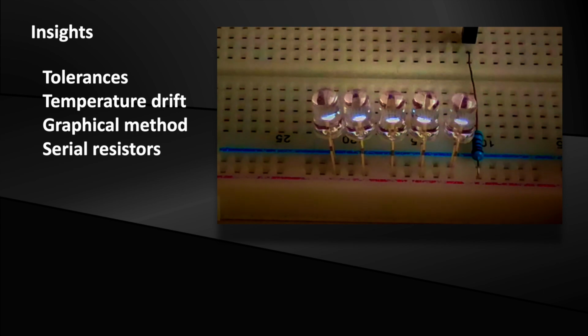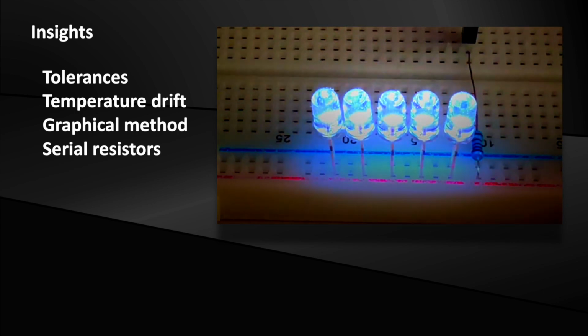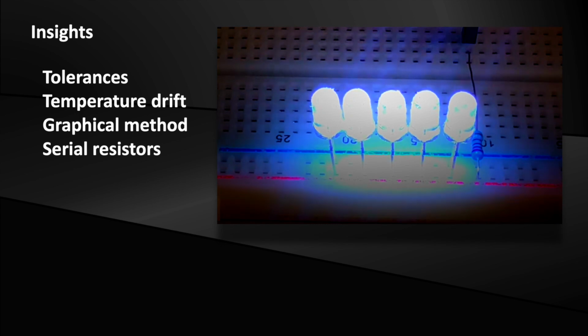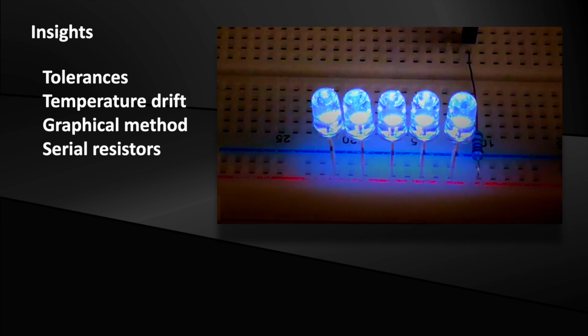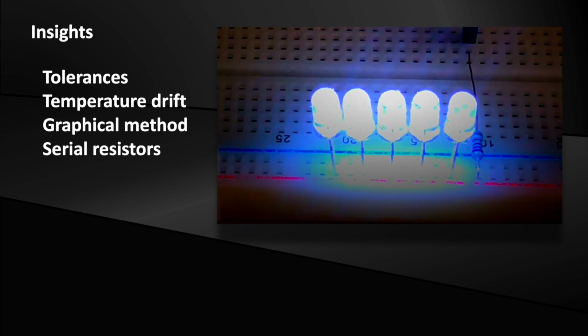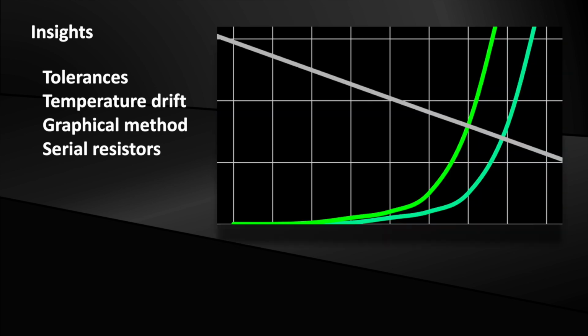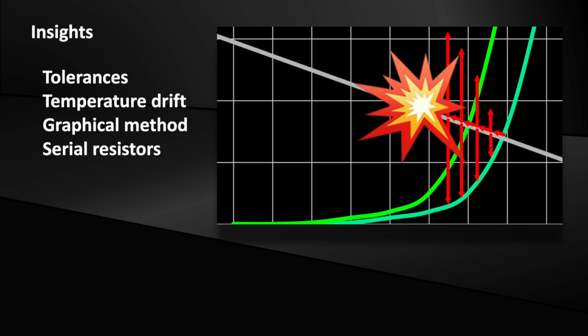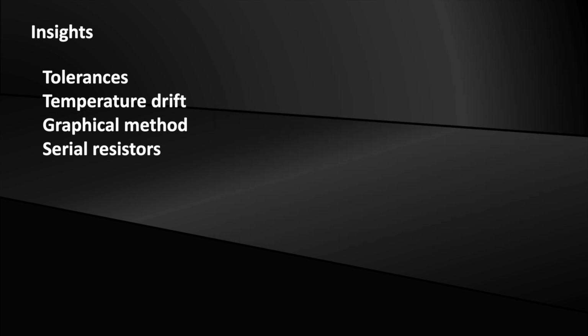Parallel connection is okay for operating same color LEDs at low current. Actually not recommended in the textbook, but possible, because LEDs today's manufacturing tolerances are small. At high current, however, it can be dangerous for semiconductors in general. Negative forward voltage temperature coefficients are driving the arrangement out of control. In case your supply voltage is high enough, connecting LEDs in series is the solution that even saves energy.